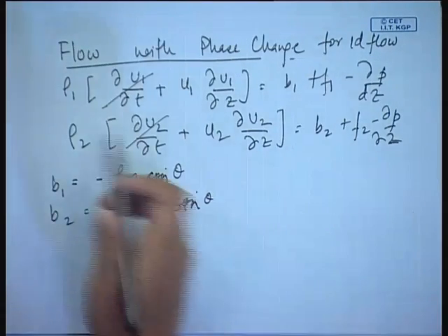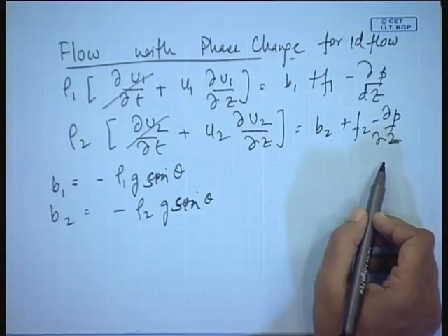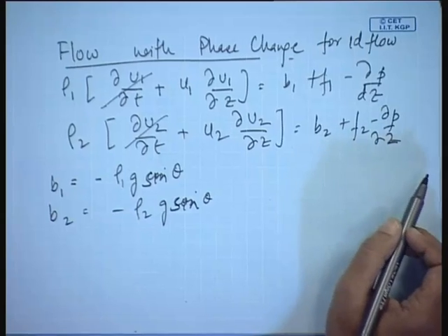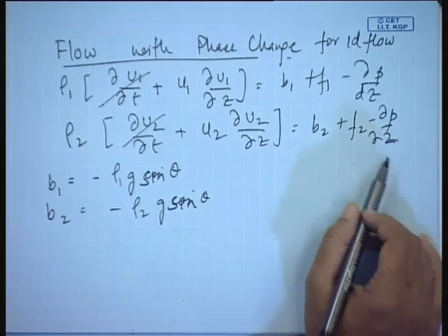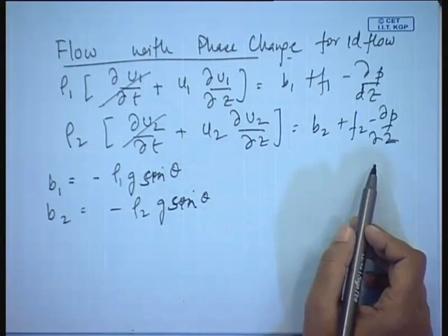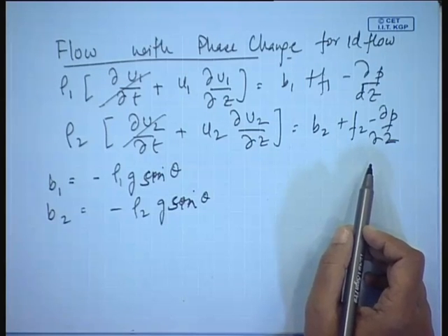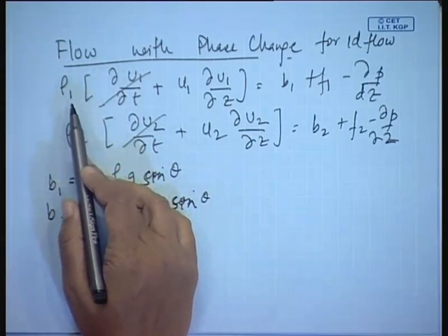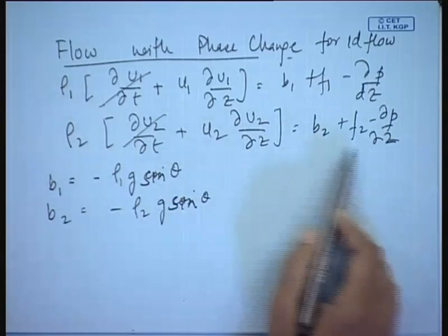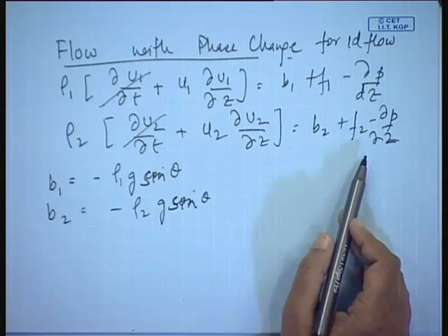So, remember one thing, these two equations are common for all two phase flow situations. We can also write down two such equations even when there is a drift, when the two phases have a strong coupling among one another, because we are just considering the two phases and writing down the momentum equation.